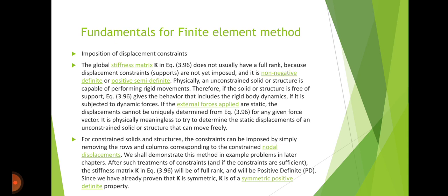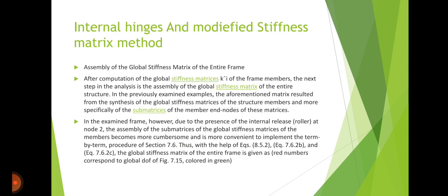After such treatment of constraints, and if the constraints are sufficient, the stiffness matrix K in equation 3.96 will be of full rank and will be positive definite, PD. Since we have already proven that K is symmetric, K has the symmetric positive definite property.